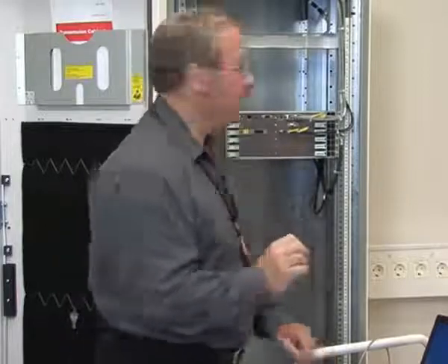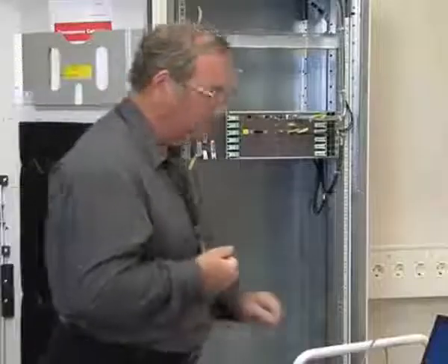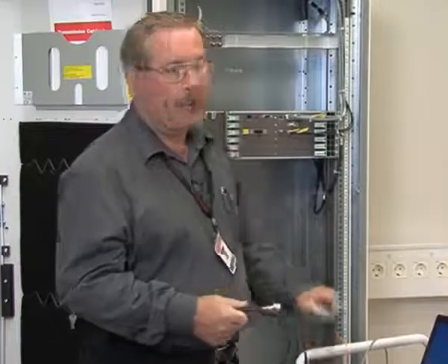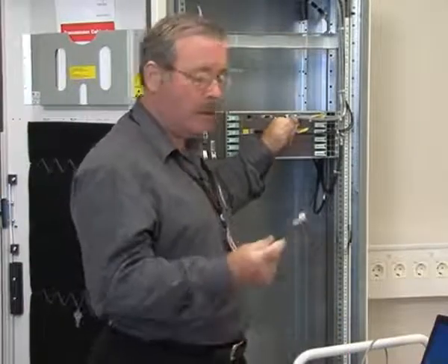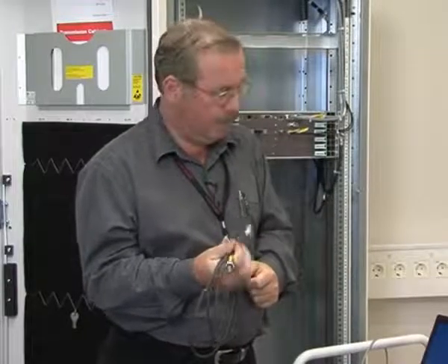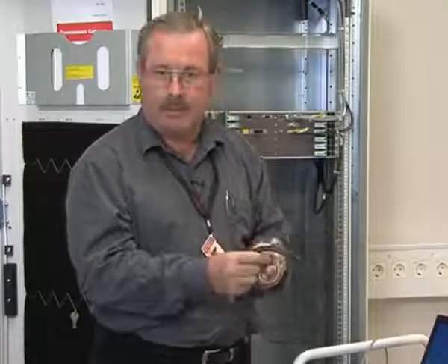We will begin with the radio terminal configuration. Begin this by switching off the power. We switched off the power because there is 60 volts DC out of this socket and we don't want to accidentally cause a short circuit. Another point is don't forget to put on the anti-static bracelet.